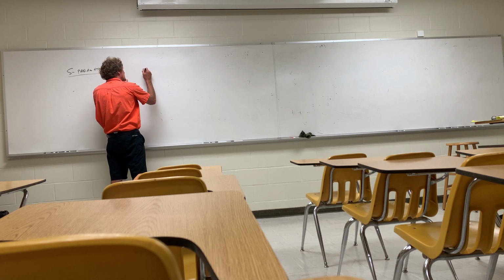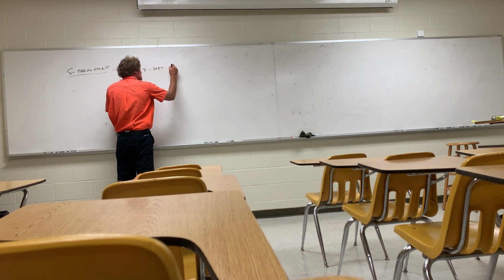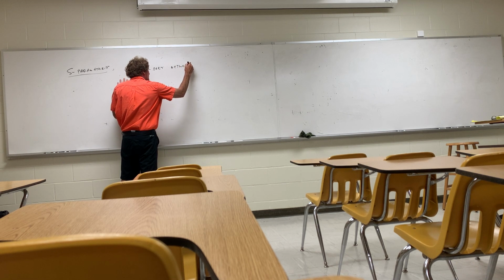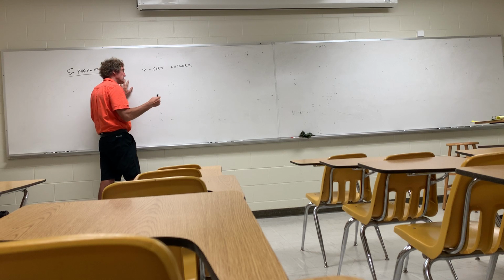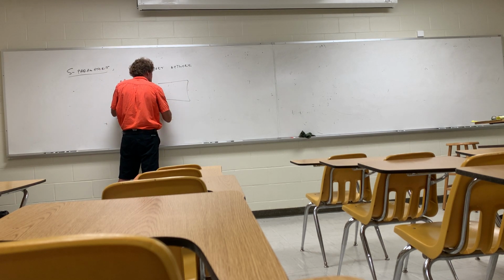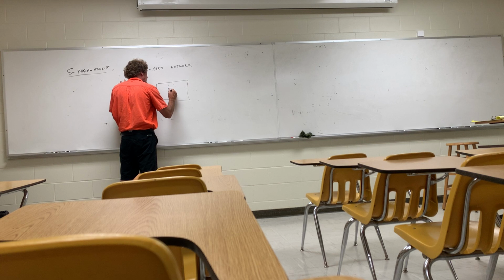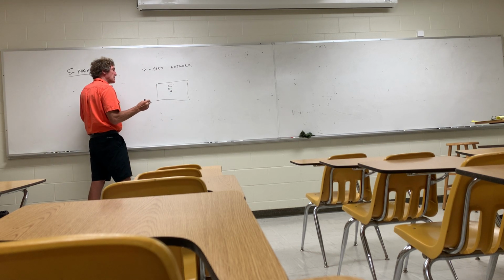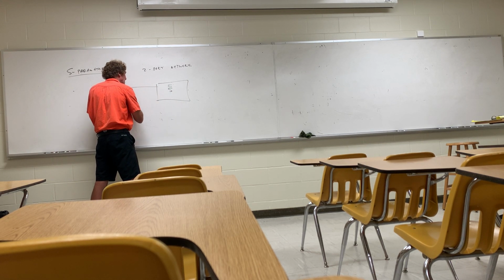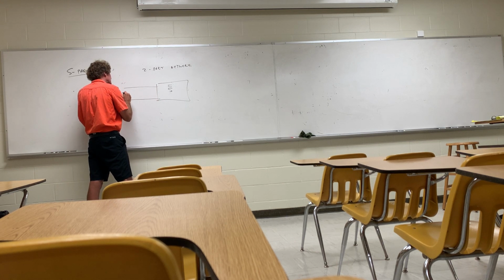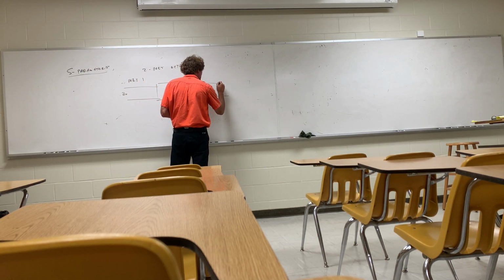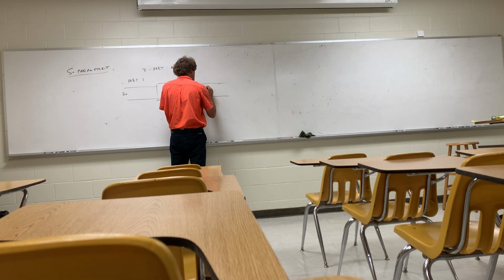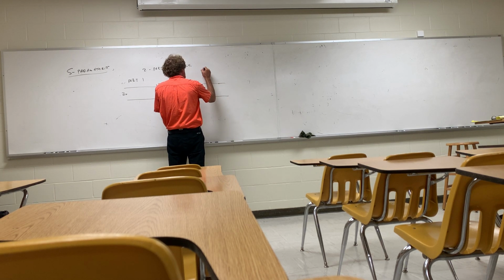We're going to start with a two-port network first. This is primarily in the microwave case, higher frequencies, but you can do it at lower frequency too. So we're going to have a device, and it's just showing us a black box. And it's going to be characterized by something called the S parameters. Here we're going to have a transmission line. It's going to have a characteristic impedance Z naught. And this will be port 1. Then we're going to have another, usually the transmission lines are the same Z naught. Another transmission line here, this is port 2.